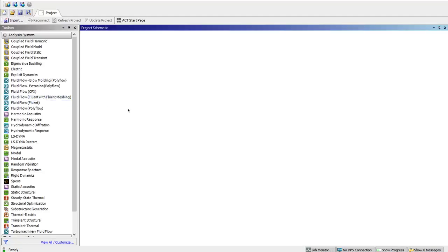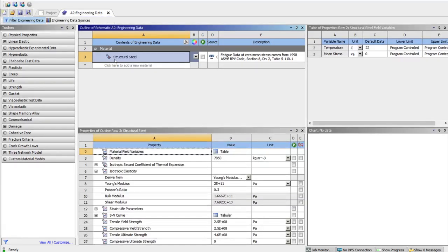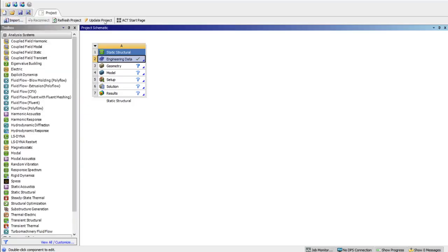So now we want to use Ansys Workbench to solve that curved beam under lateral loading. So we need a static simulation, so we use the Static Structural module here. And once it is loaded, we can first look at Engineering Data, where we can see what material is available to us now. The material selected is structural steel. This is the right material for this problem.